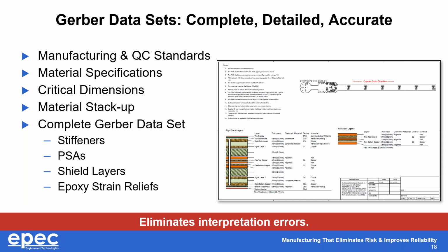Identifying critical dimensions, ensuring that the correct and detailed material stack-up is part of the data set, ensuring that the data set is complete for the Gerber files.